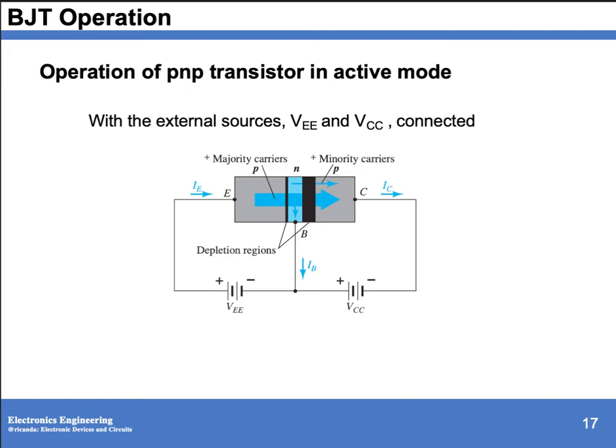The reason for the relative ease with which the majority carriers can cross the reverse-biased junction is easily understood if we consider that, for the reverse-biased diode, the injected majority carriers will appear as minority carriers in the N-type material. In other words, there has been an injection of minority carriers into the N-type base region material. Combining this with the fact that all the majority carriers in the depletion region will cross the reverse-biased junction of a diode accounts for the flow as indicated in the figure.